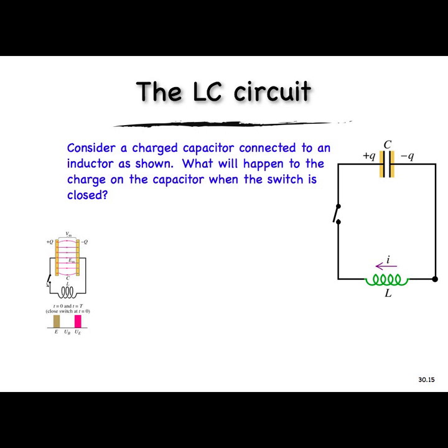And that large EMF produces a high voltage between these two terminals that actually causes an arc. So it breaks down the air, ionizes the air, and allows the current to flow through that ionized channel. That's basically lightning. And so the current keeps flowing even though there's no longer a metallic contact here. It breaks down the air and flows through the air to complete the circuit. So that's just an example of how much the inductor will try to keep the current flowing.